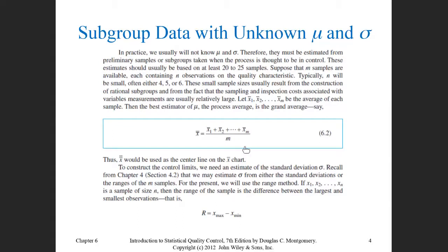What I would like to highlight here, and it is very important, is the sample size and the frequency of the sample of the control chart X bar R, because this is one of the decision criteria when you decide whether to use X bar R or XS: the sample size and the frequency. If the sample size is up to 6, this is a decision criterion, and you have variable data, you use X bar R control charts.